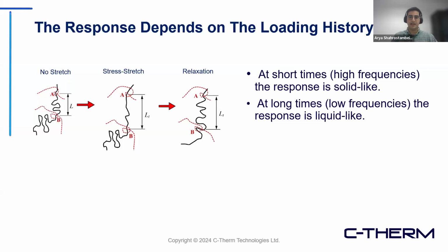Talking about those 2 sentences about the effective frequency of your material, short times and long times, I mentioned that the response depends on the loading history, which can be frequency. What is happening behind that is the relaxation time. If you apply force, let's say stretching your sample quickly with higher frequencies, your material stays on the stretched chain of the polymer.